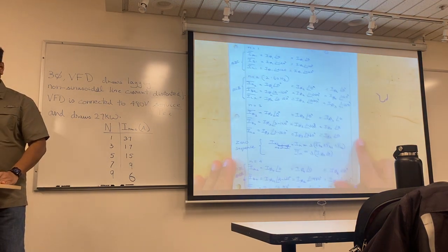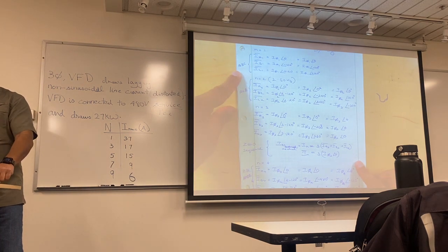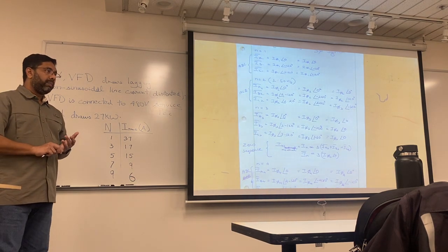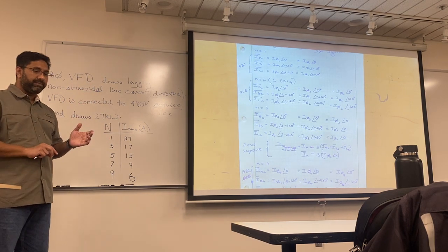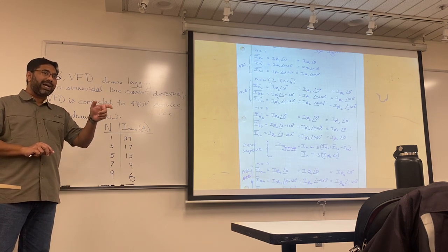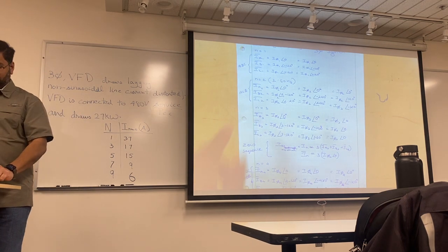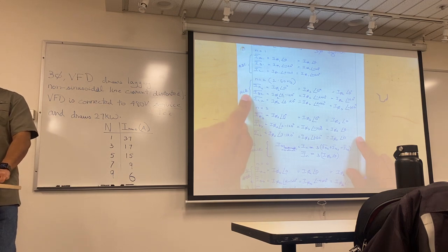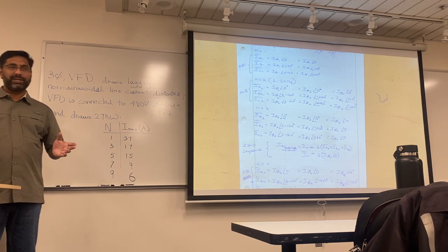So without doing a whole lot of wiring, what has happened is you guys went from an ABC sequence to an ACB sequence. This is a big deal if you are running a motor, especially. Motors depend on the right winding. So you have to connect A to A phase, B to B phase, and C to C phase. They also expect a rotating magnet to come in like, they expect the first A, then the B, and then the C. Look here what's happening. Just because there is harmonics, the motor is actually going to see ACB, and it might stall, it might jerk, it might overheat, all kinds of nonsense can happen.